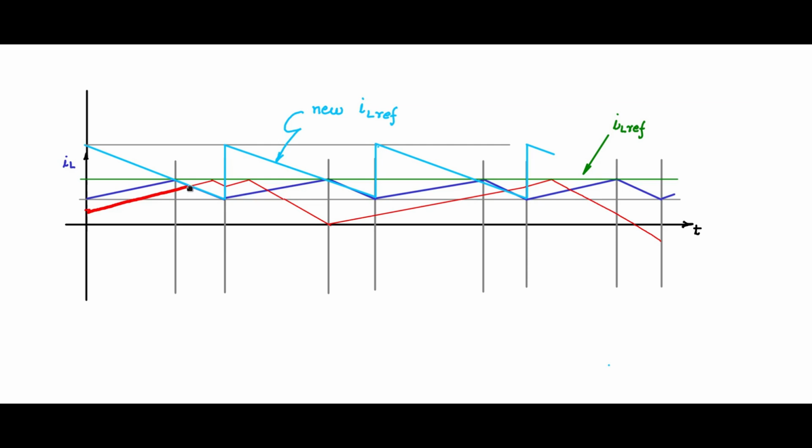It then starts having a downslope along the same parallel, because the falling slope of the inductor current is minus V0 by L, or minus VB by L in this case. So you see that in just one switching cycle, the error has been reduced, and from there on the current continues to follow the steady state value. Any error quickly converges and is removed within a switching cycle.